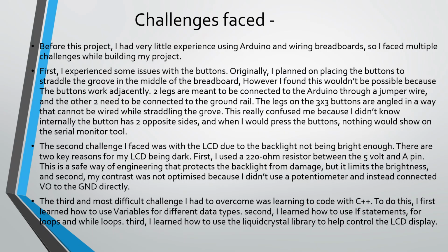For this project, I had very little experience using Arduino and wiring breadboards, so I faced multiple challenges while building my project. First, I experienced some issues with the buttons. Originally, I planned on placing the buttons to straddle the groove in the middle of the breadboard, but I ran into issues with this because the 3x3 buttons have 4 legs that are angled in a way that cannot be wired while straddling the groove. The buttons work adjacently, so 2 legs are meant to be connected to the Arduino through a jumper wire, and the other 2 need to be connected to the ground rail.